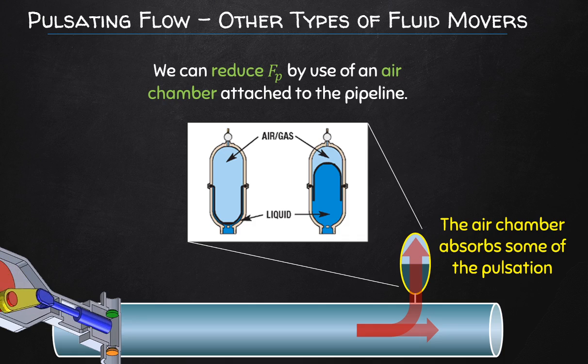Generally, in industry, we like to pump liquids. It's cheaper. Volumetrically, you can pump more in the same diameter of pipe, and it's better in terms of storage and handling. But in some cases, like with hydrogen, you're not going to want to pressurize it to liquefy it, because that pressure is just going to be ridiculous. I think it's like 700 bar. Can you picture that? That is quite crazy.